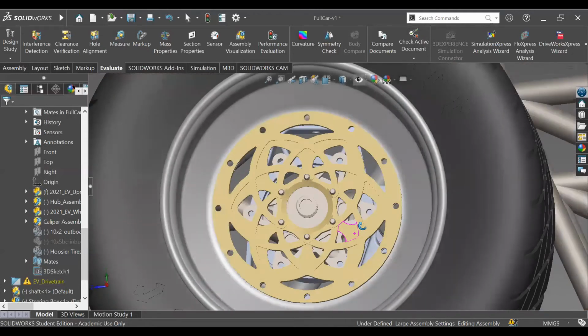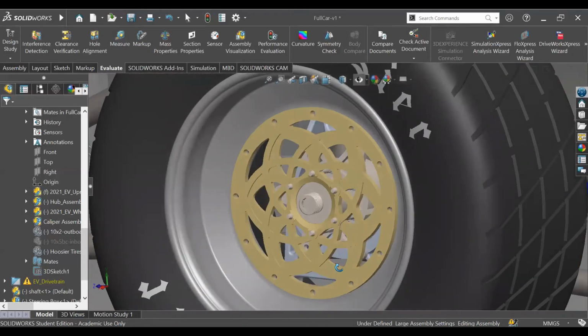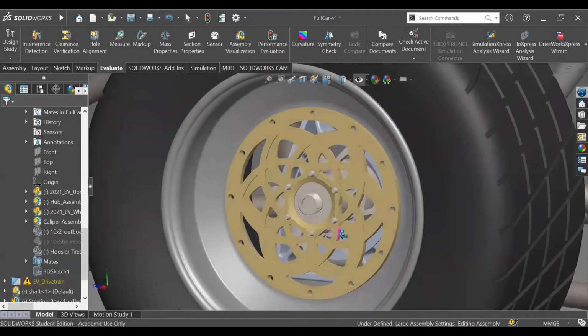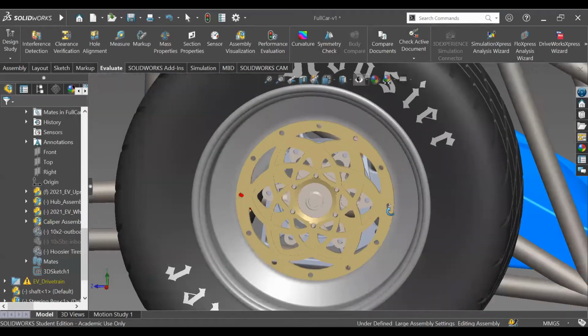It's a pretty good looking wheel center. A difficulty that we had was designing this around it being manufacturable. That meant taking away some chamfers and fillets, thickening up some thin members, and rounding off some sharp corners. In terms of rules, the wheels have to be 8 inches or more in diameter. Our wheel shell, which is this silver portion, is 10 inches, so we meet this rule.